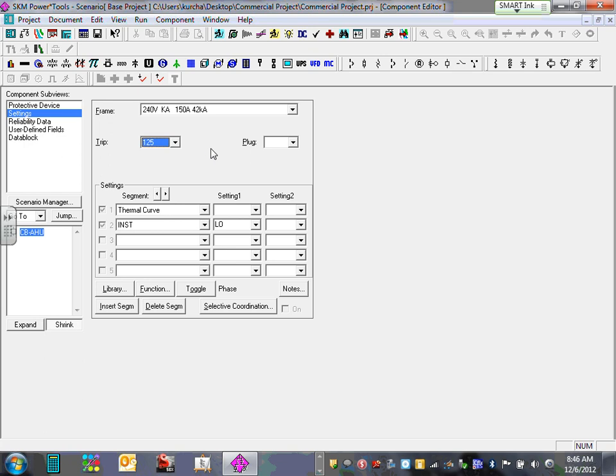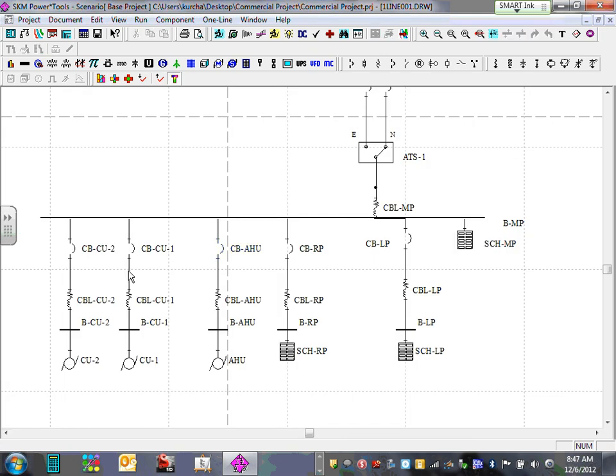Did you see what I did? I grabbed 150 at the top and I adjusted it to 125. That's tweaking it right in the front of it. I made this circuit breaker adjustable to 125. Everybody get that? That's my circuit breaker for the air handling unit. Cool. Okay, now I'm going to go to the chiller. Let's go to chiller number 1.